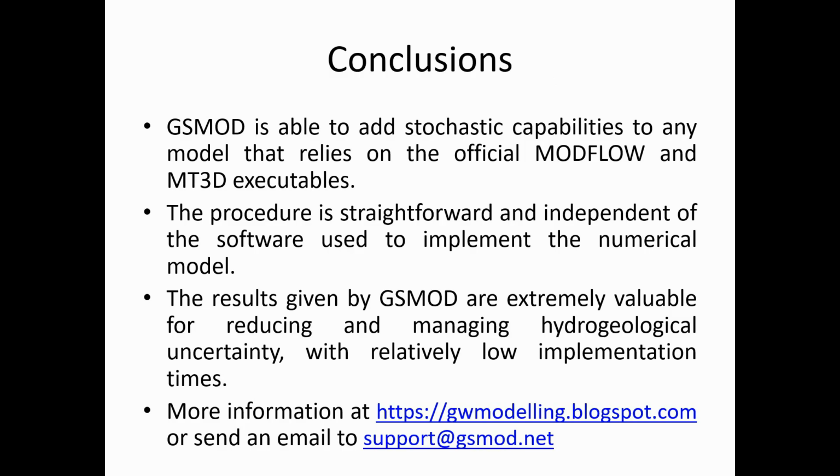Finally, the most important conclusions associated to the use of GSMOD are presented. GSMOD can add stochastic capabilities to any model that uses the official MODFLOW and MT3D MS executables. The procedure is completely independent of the original modeling software. The stochastic results generated by GSMOD are extremely useful for studying and reducing hydrogeological uncertainty.